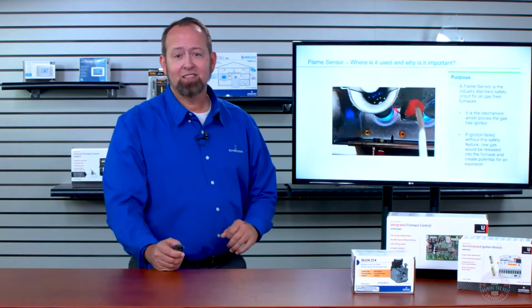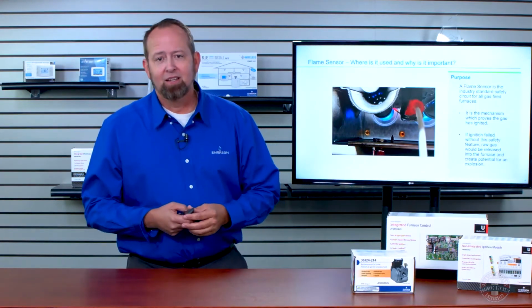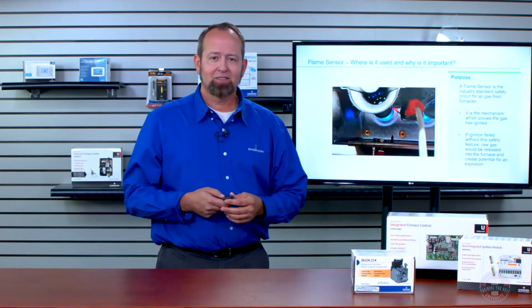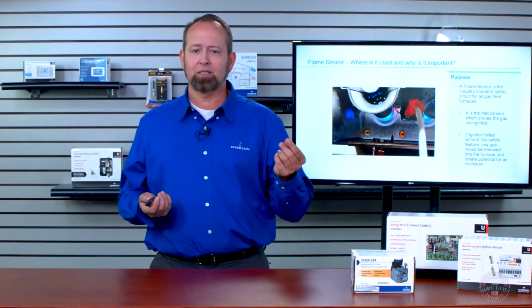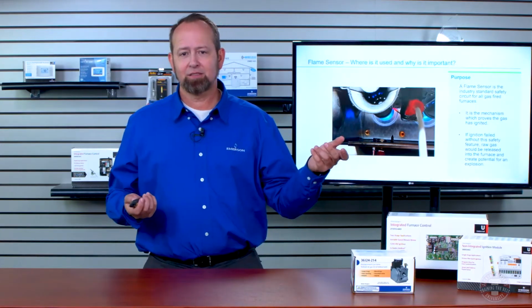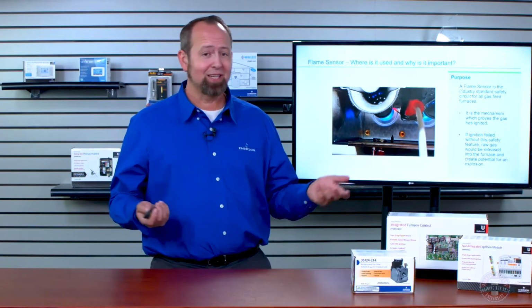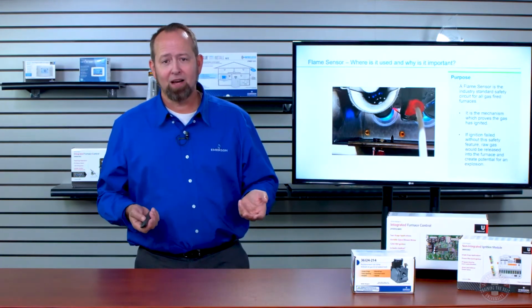The next section that I have is on flame sense and flame sensors. And flame sensors, you'd think, yeah, this is something pretty simple. It's just a metal rod that goes in front of the flame, and it senses that there's flame there. There's no relays, there's no moving parts. It's just a simple rod.